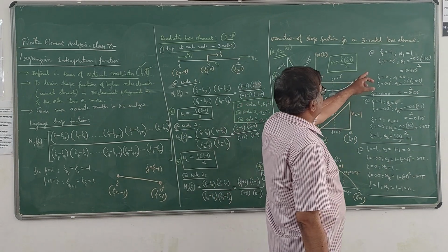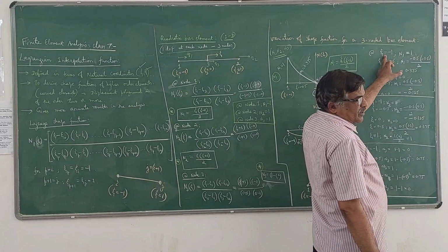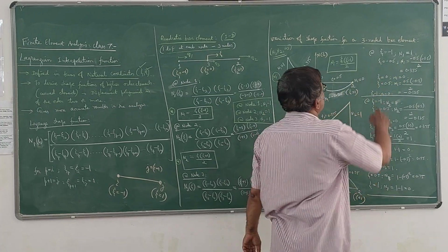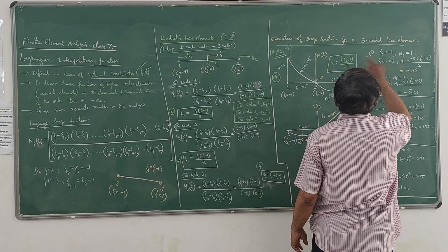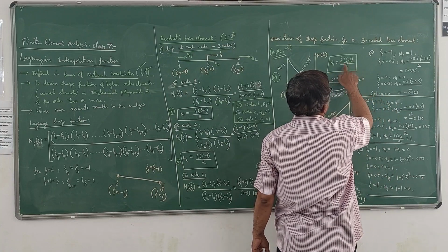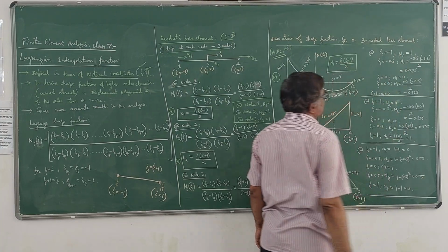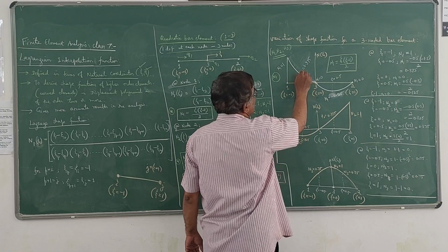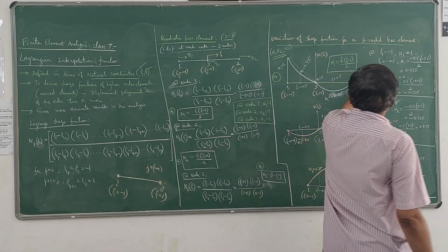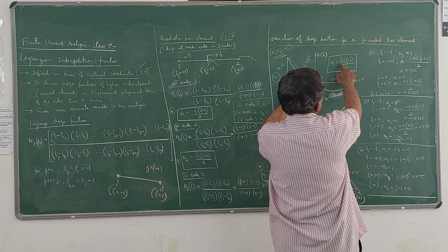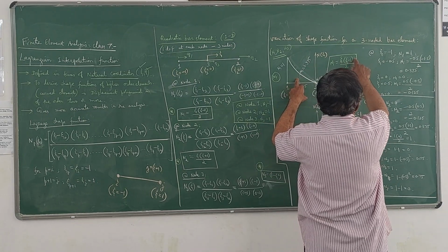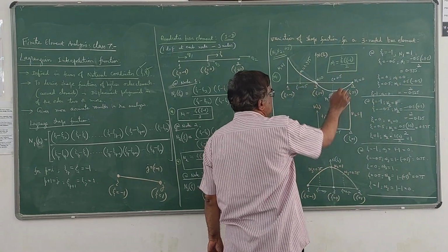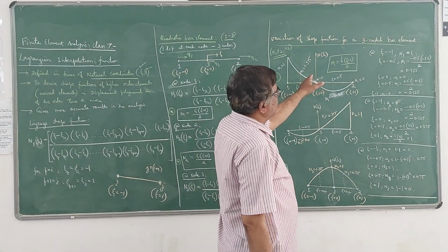Now you can observe here, I have substituted values of zeta in this expression and got the corresponding values of n1. If zeta is -1, n1 will be minus 1 into -1 divided by 2, which becomes 1. You can calculate that. Then at this point, zeta as minus 0.5, substitute here, you get minus 0.5 into minus 1.5 divided by 2, which becomes 0.375, which is positive. Please note that positive values I am plotting above the line, above the element.